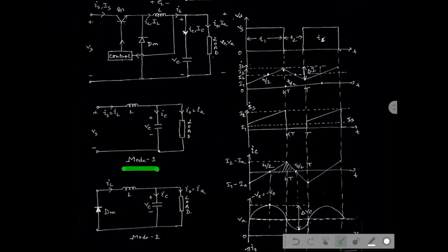So think about the first mode of operation. When the switch is on, the inductor starts storing energy and the current gradually increases from its low value I1 to capital I2 during T1. And the voltage appearing across the load is Vs. Okay. And when the switch is off, what happens? In the first mode of operation, when the inductor gets charged fully with respect to the supply voltage Vs, the polarity of the inductor was like this.